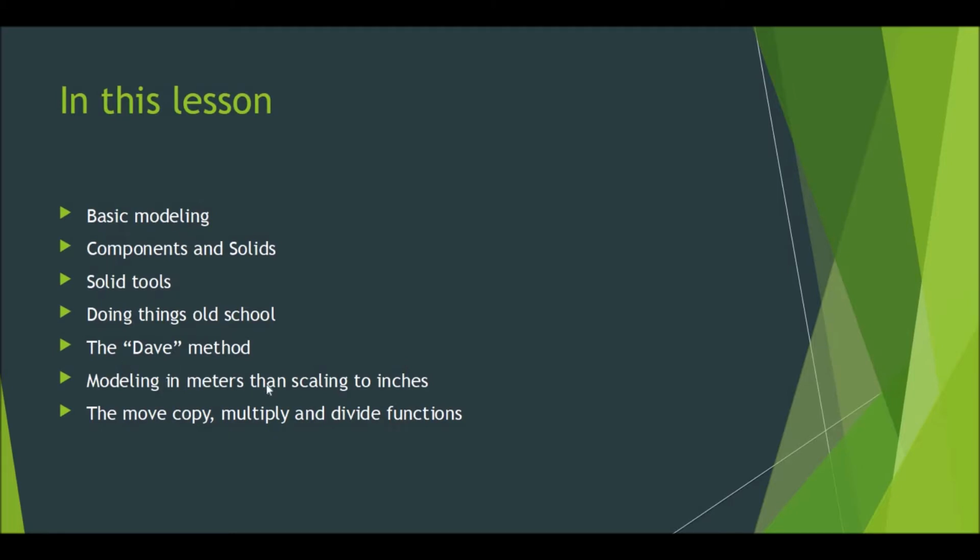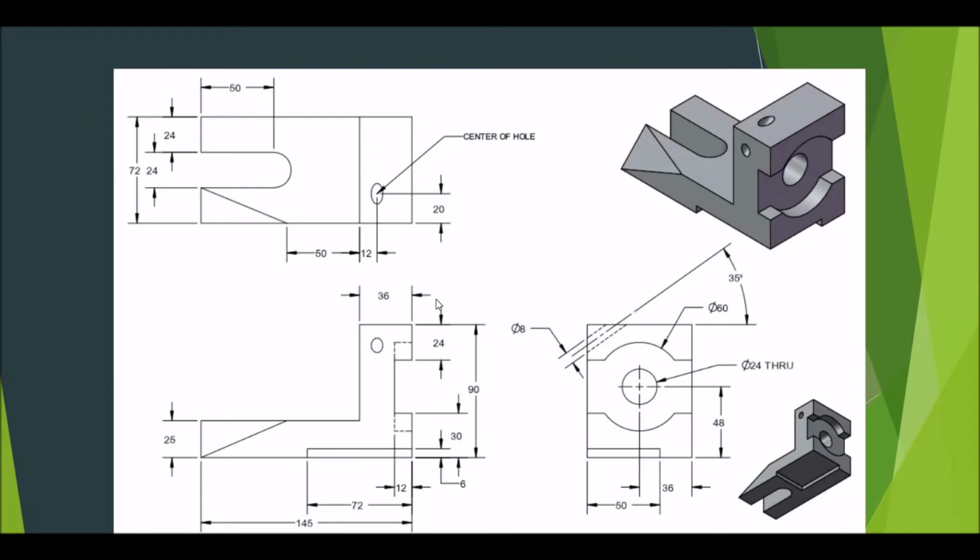We've done modeling in meters and then scaling to inches, but this might be a good time to review that. And then the move, copy, multiply, and divide functions. You saw me do that with the rotate in chapter 2.5, but now we're going to try it with the move function. So this is the part we're actually going to make.